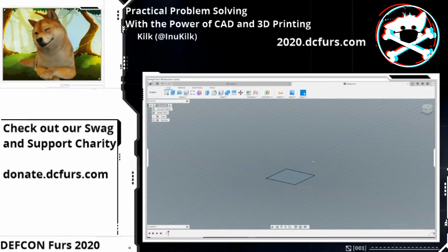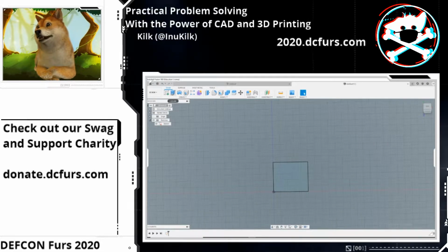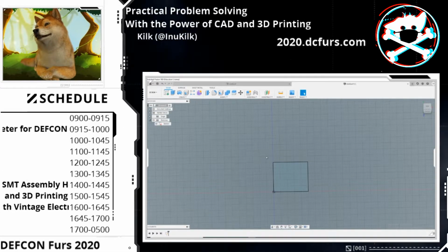So this is important to know. If your sketch for some reason doesn't show up, maybe it's because if you drop down the folder here, and you see the eye icon slashed out, it means your sketch isn't showing up. You want to click that. This is important because if we're selecting for an extrusion, we need to see that sketch.